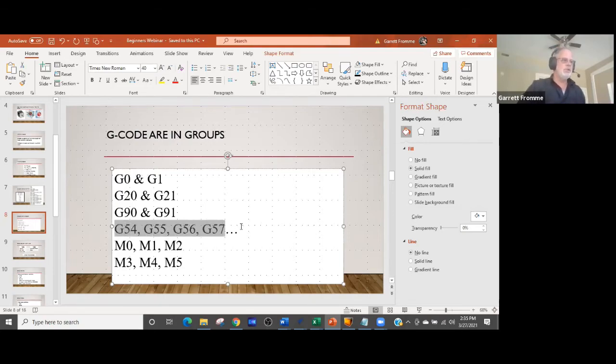You'll see G54, 55, 56, 57, 58, and 59 are part of a group, and you will always see G54 on your controller. I have a video out there that talks about this. These are used when you want to produce things. And then, of course, you have your M codes, which are telling your spindle to turn on, turn off, to stop the machine temporarily, or to end the program.